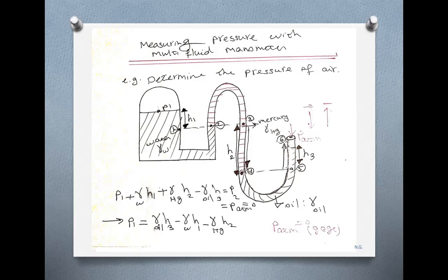And then we reach point 4 and move horizontally, since we know it's going to be the same pressure at the other end. So we reach point 5, and from point 5 we are going up, so it's going to be a negative H3 gamma of that liquid over there. And then as you explained, it's equal to the atmospheric pressure, which is 0. So from the following, we can write the equation that you have over there, Professor. You explained perfectly. Thank you.